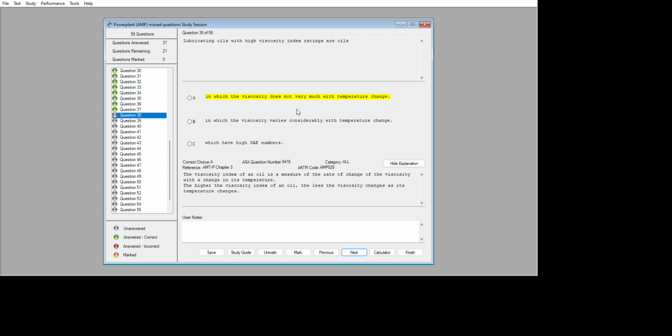In which of the following situations will the oil cooler automatic bypass valve open the greatest amount? Engine oil below normal operating temperature. Oil picks up most of the heat from which of the following turbine engine components? Turbine bearing.